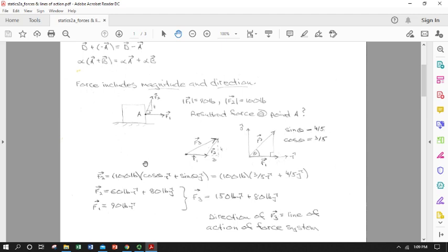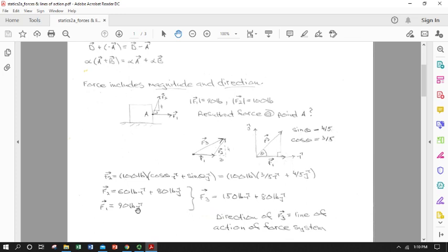So I'm going to distribute that 100 pounds over the x and y components, and I'll evaluate cosine theta using my little fraction and multiply out, and I actually get whole numbers, which is convenient. So I end up with 60 pounds in the x direction, which is horizontal, and I get 80 pounds in the vertical direction. Now I had F1 as well, which was 90 pounds, and it was all in the horizontal or i hat, meaning unit vector in the i direction.